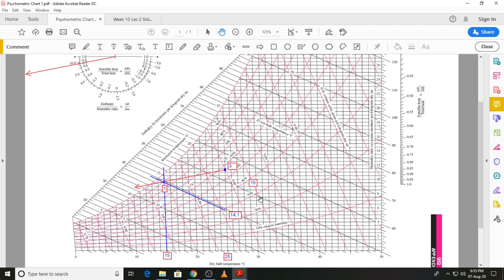And then we had performed the energy balance to find the volume flow rate entering the room, and to do that we required the values of the enthalpies at states 3 and 1, and also the specific volume at state 1. I will move on to the enthalpies first, then I will come to the specific volume.